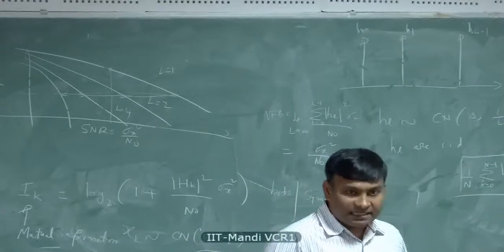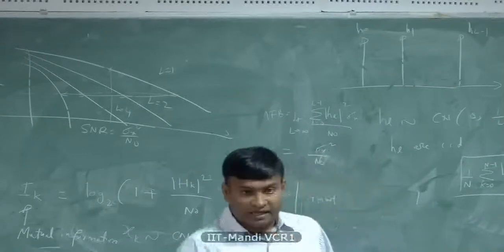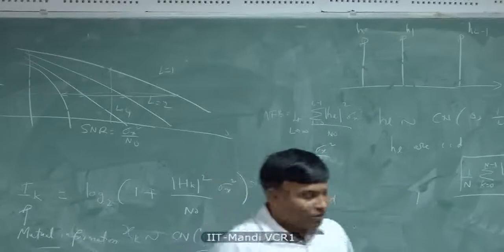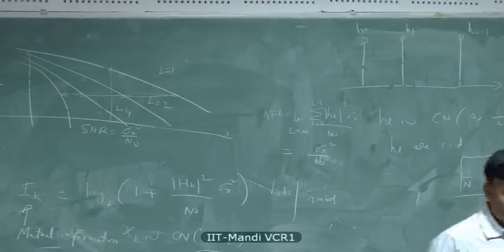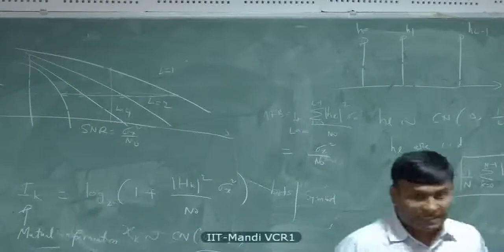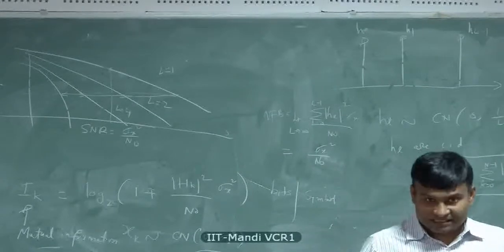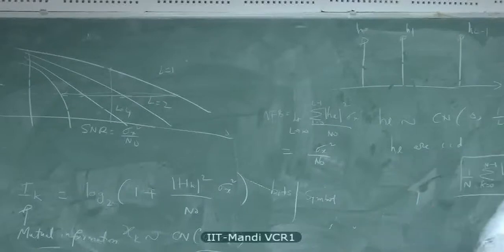So what you do in that case is use multiple antennas at the receiver and separate these antennas with sufficient spacing, several wavelengths apart, and hope that there is this scattering, and combine the outputs of these antennas and you get antenna diversity. Well, it will still give you an effect like this, where this L is no longer the number of multipath taps, it is the number of antennas.